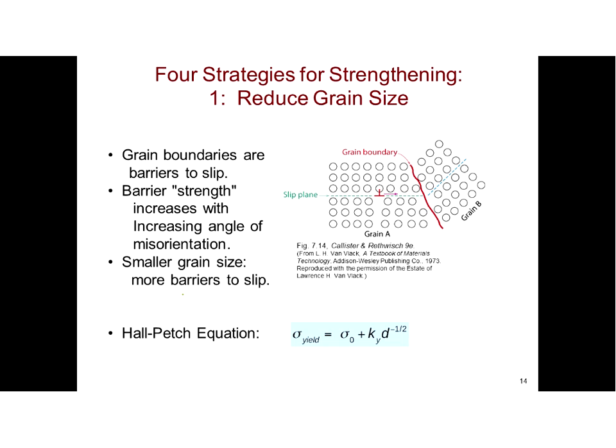We're now going to talk about this as a mechanism for strengthening materials. It doesn't mean that polycrystalline materials are a bad thing. In fact, if a grain boundary makes a material stronger, hey, let's make some more grain boundaries, right? We can increase the strength of a raw material. Instead of having it be perfectly crystalline, let's create some grain boundaries. We've already said that these grain boundaries are barriers to slip. If we were looking at a slip plane and this extra half plane of atoms moving towards the grain boundary, it's going to meet a dead end at the grain boundary.